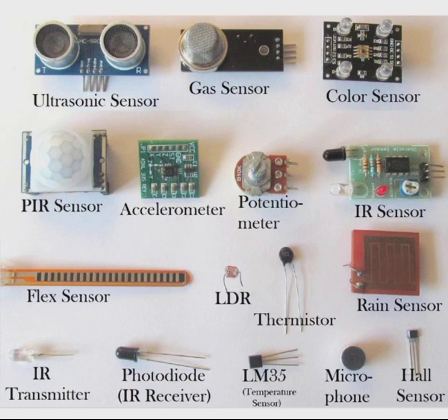Here on the screen you see that the first category is the ultrasonic sensor. It has one transmitter and one receiver, and it operates on the principle of sending and receiving ultrasonic waves into its surrounding. It is used in applications to detect an object, to detect positions and movement, etc., and it generates a proportional electric signal in response to the ultrasonic waves that it receives.